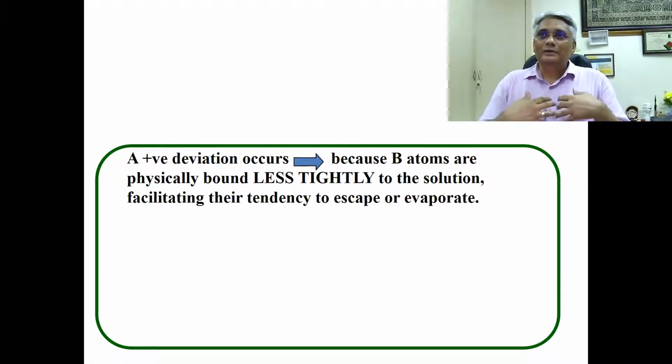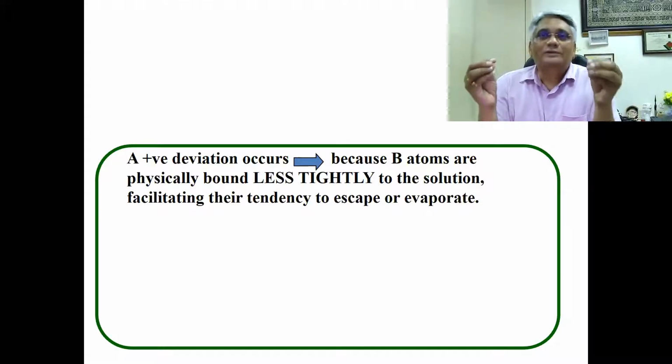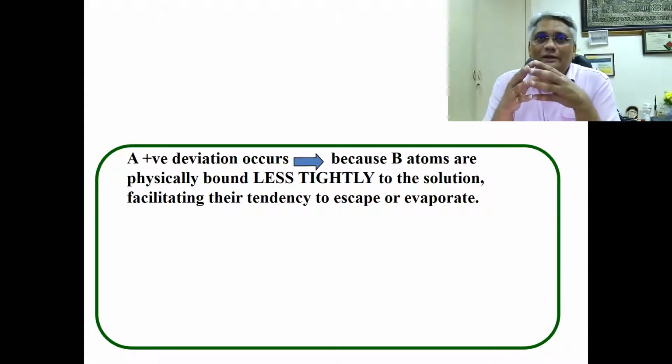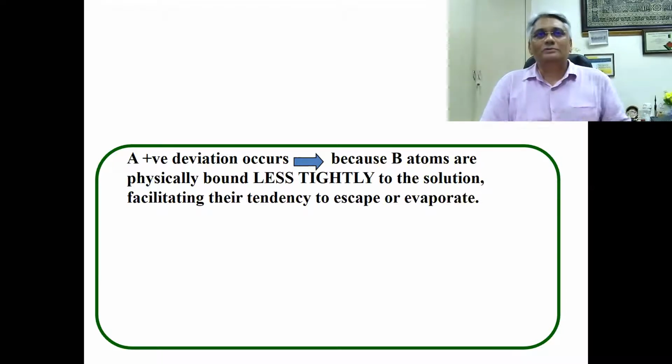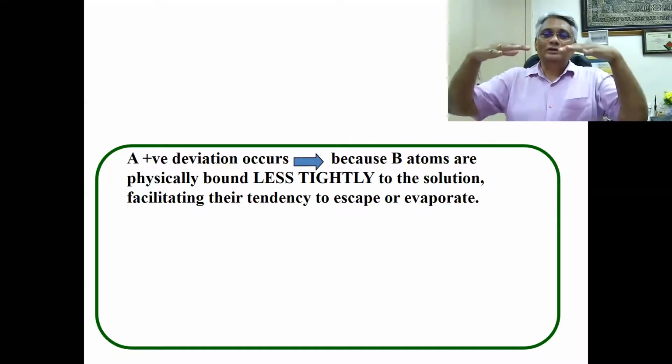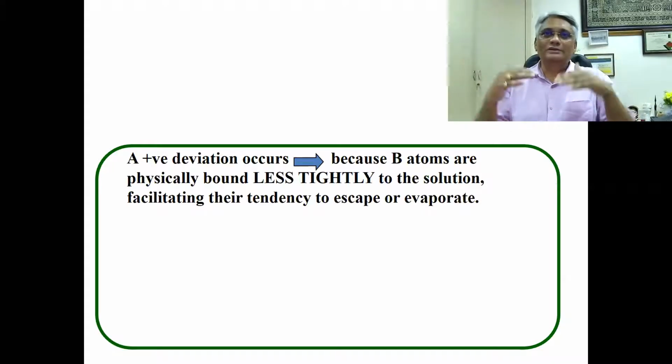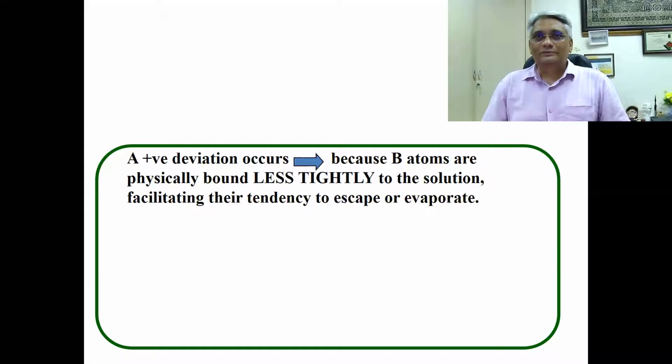Metal atoms can be separated out from the alloy easily, which means that in the thermal evaporation process of alloys consisting of 2 or 3 or 4 elements, in most cases you'll see the elements coming out of the matrix, the charge, as separate entities, not as AB or ABC alloy composition.